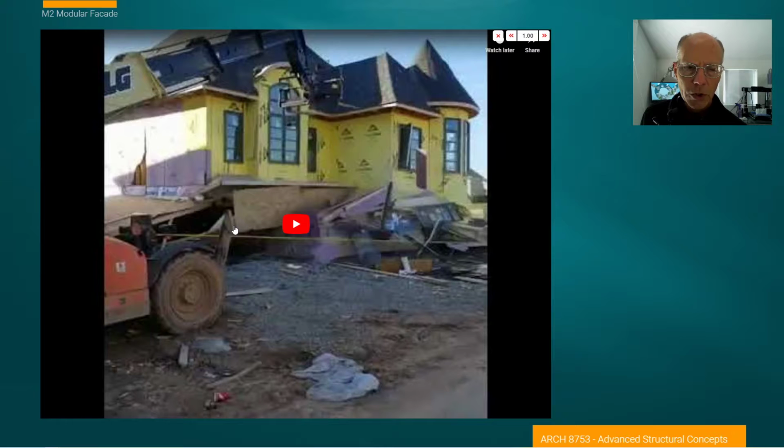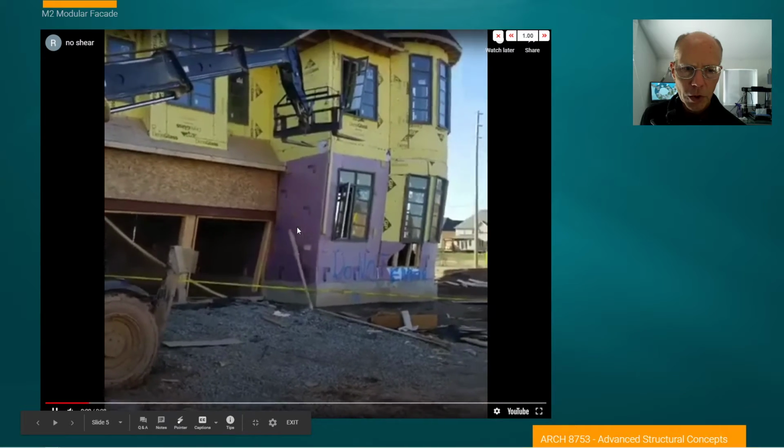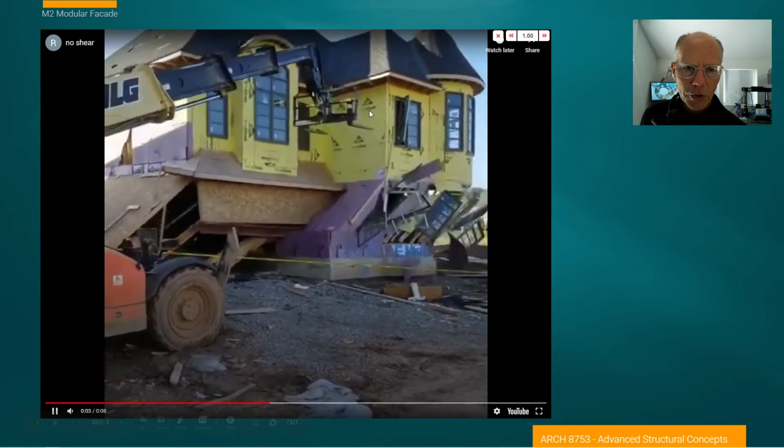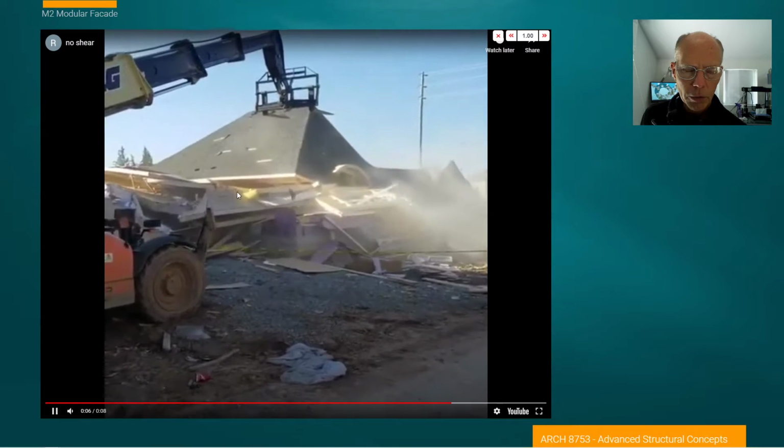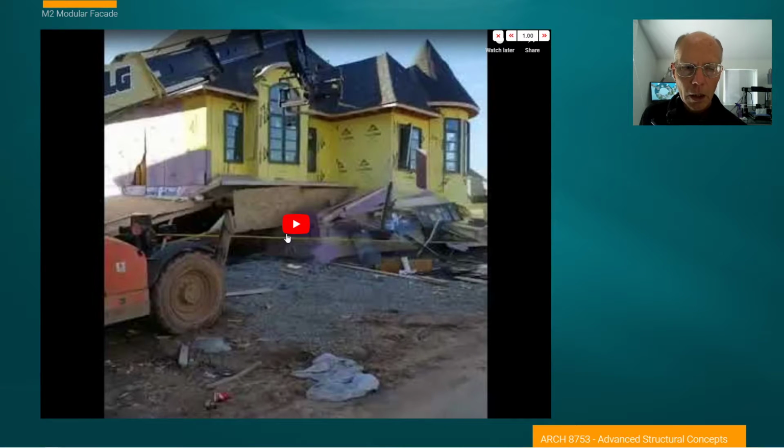But one of the things that it makes you think about is how weak these structures can be if they don't have proper shear wall construction in them. And one of the problems with the exterior sheathing systems that we use in a lot of our new building materials, and we're substituting out plywood, is to pay attention to what the sheathing is and to realize that the function of these exterior walls, the way they're fastened in, become part of a shear wall performance. Now, in our project, we're actually making curtain walls, so we don't have the necessary requirement of shear wall performance, but we still have this idea of resisting lateral forces, and so I wanted to punch up on this issue. We're going to discuss it a little more.